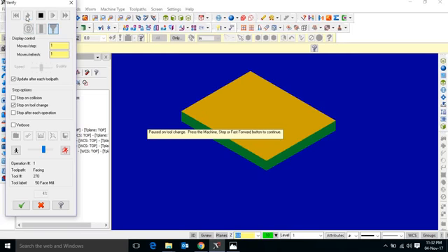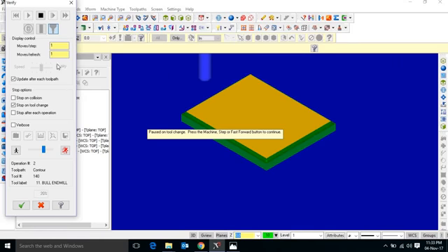Play. In this way the facing operation is completed. Again play. The contouring operation is completed. There is no collision of tools, so the machine stops automatically. The contouring operation is completed, so the machine is stopped. For the next operation, play. There is a center drill 5 mm and 2 mm depth. Again play. Through depth.